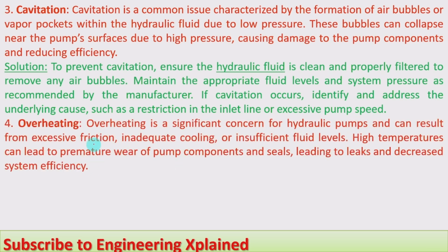Next one, fourth, overheating. Overheating is a significant concern for hydraulic pumps and can result from excessive friction, inadequate cooling or insufficient fluid levels. High temperatures can lead to premature wear of the pump components and seals, leading to leaks and decreased system efficiency. The overheating is due to friction, inadequate cooling of the system, or insufficient fluid levels.